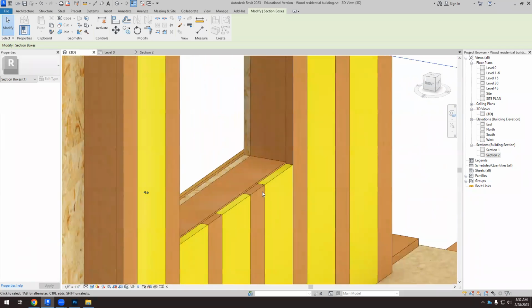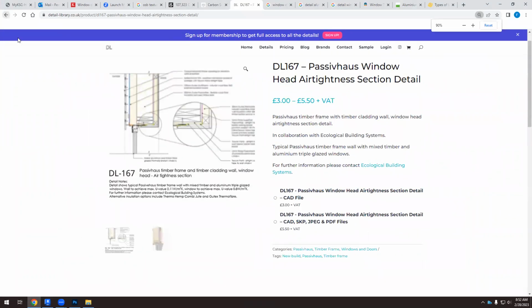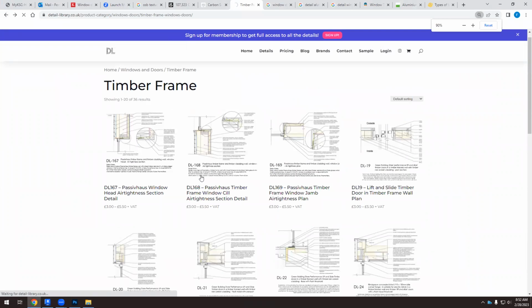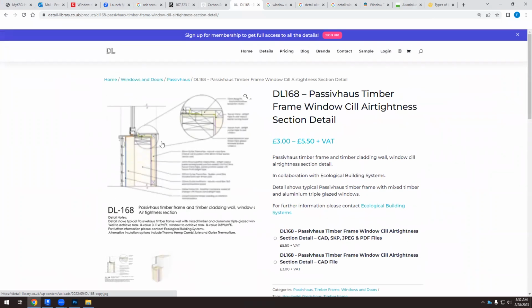So first, what do we have? We have this. So remember that at the top of this thermal insulation, I have to create that first square element. This one. And I'm going to use an option that I think we have used before. It's the sweep option. So we're going to create a sketch, and then a profile, and then we're going to move that sketch along a profile. And I think we're going to do this different times with all these elements that we have in the window.